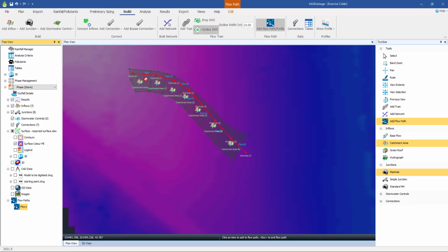This session is all about pipe design, and the first thing to focus on is the fact that it is purely sizing of pipes and placing them at the correct depth and gradient below the ground. We haven't begun to talk about the design of storage or SuDS, BMP, LID features, anything like that. This is purely focused on pipe design.